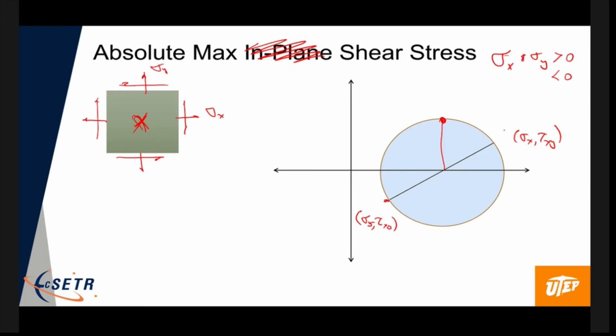We haven't talked about rotating anything other than in the plane. So there still is the zero stress out of the board. So there actually is a normal stress coming out of the board. This is like a sigma z, and if it's a planar state of stress, that corresponds to 0. In fact, that puts a point on Mohr's circle right there.